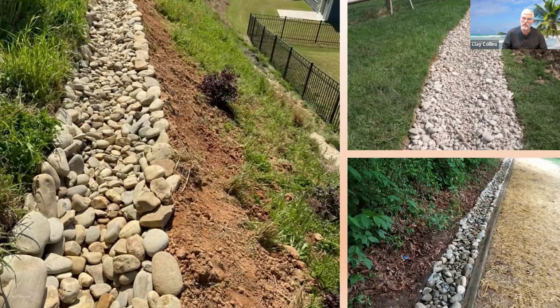You see on the French drain in the large picture on the left, you have water running down into that trench filled with rock to prevent it from going down that slope towards the house. That is not a barrier so much as it is a very shallow French drain, and you see it's effective because that soil hasn't eroded. You've got some spots, but it just hasn't eroded the way you might expect if it were running down that hill and simply across.